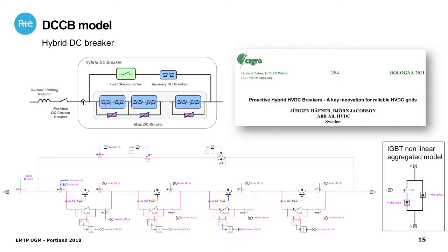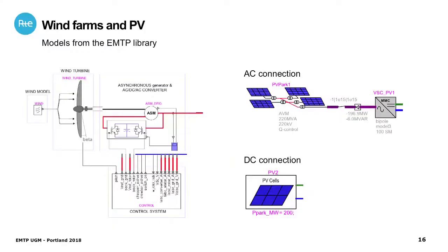The value of the nonlinear characteristic is based on the data we received from the manufacturer, because outside this working group we have some collaboration with ABB, so we have some data available, and the characteristic has been modified in order to be realistic. And the same for the other valves that are here. The surge arrestor characteristics are modified in order to take into account the voltage level.